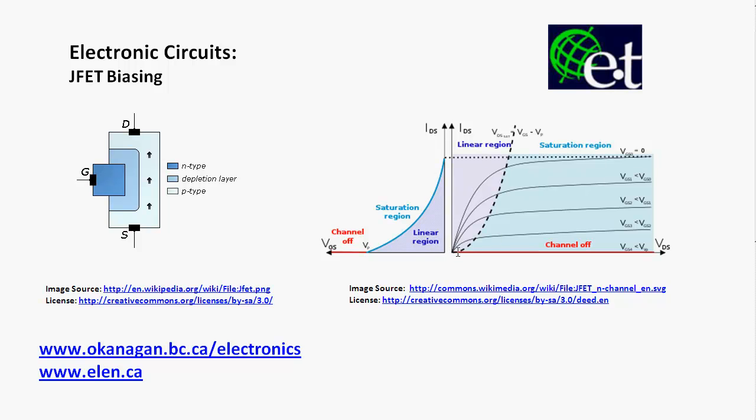But if we pick any particular curve and we consider increasing and changing the value of the drain source voltage, so let's look at this one. This one's the most extreme one. As we increase the drain source voltage, the drain current increases in almost a linear manner, up to around this point or so. And so as you increase the drain source voltage, the drain source current is going to be increasing up to a maximum. And then once we reach that maximum, increases in drain source voltage result in very little increases in the drain source current.